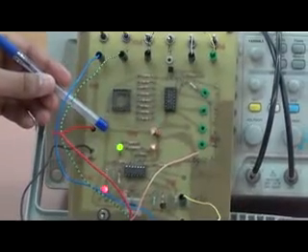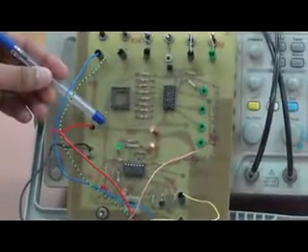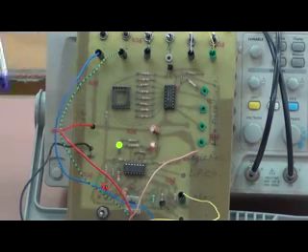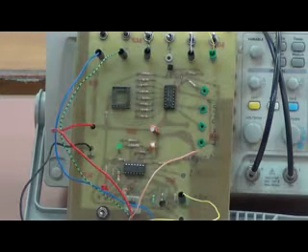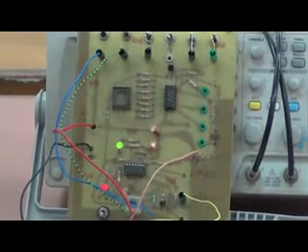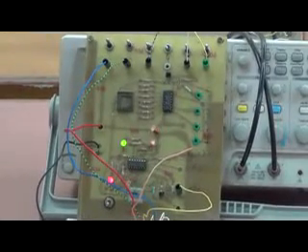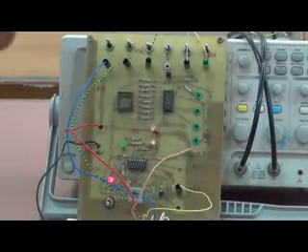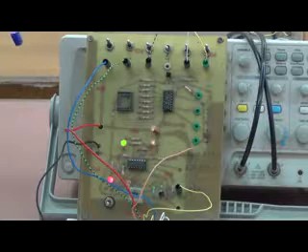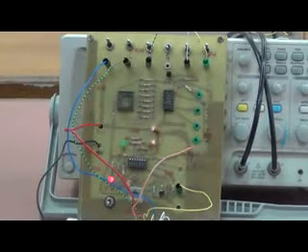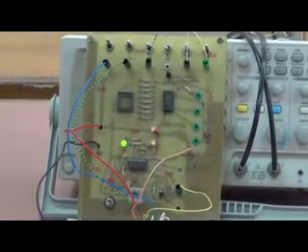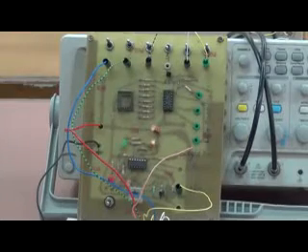So it will always toggle between 1, 0, 1, 0 depending on the previous condition and on the clock pulse. Since this IC is positive edge triggered, whenever a positive edge of the clock comes, it toggles from 0 to 1 or from 1 to 0. Hence this verifies the truth table of this JK flip-flop.